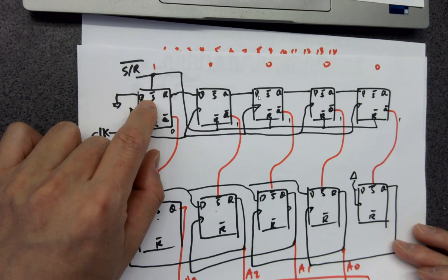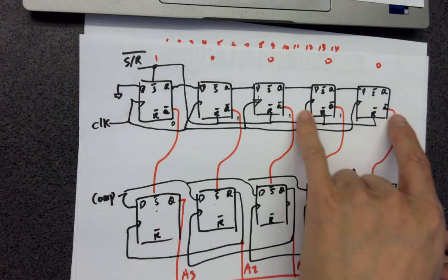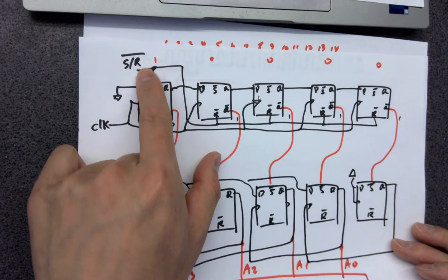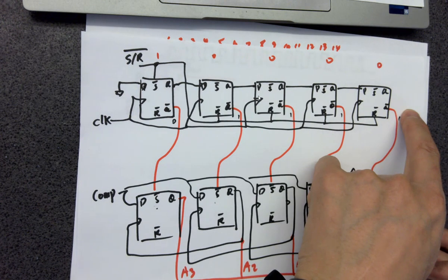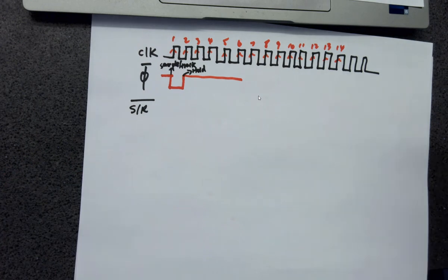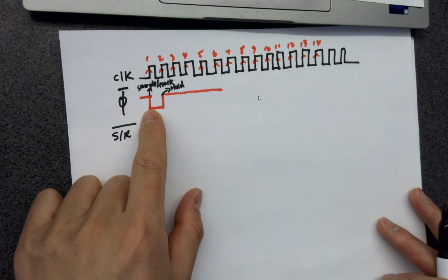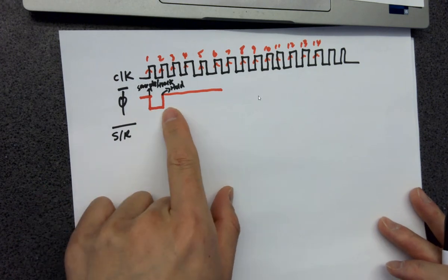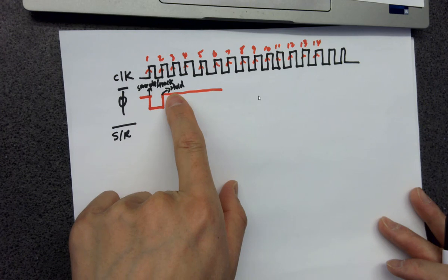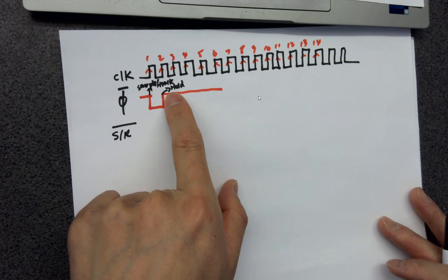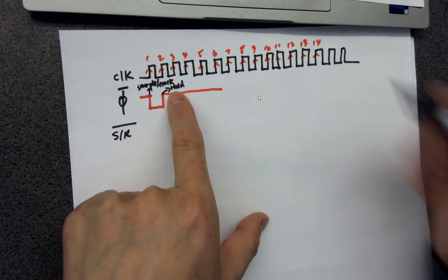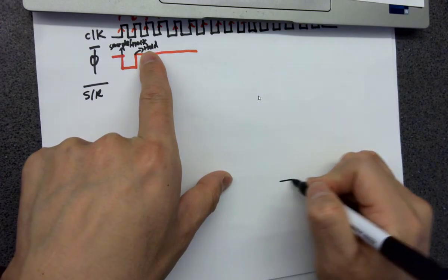It's a set for the first one, but just reset for all the following ones to generate that 100 state. Remember that in the ADC's algorithm, the first little circle is 1 and all zeros, right? You don't want to do it here because it's not ready yet. And whenever you generate that state, you want this DC value available, because this is the DC voltage. Remember that diagram?